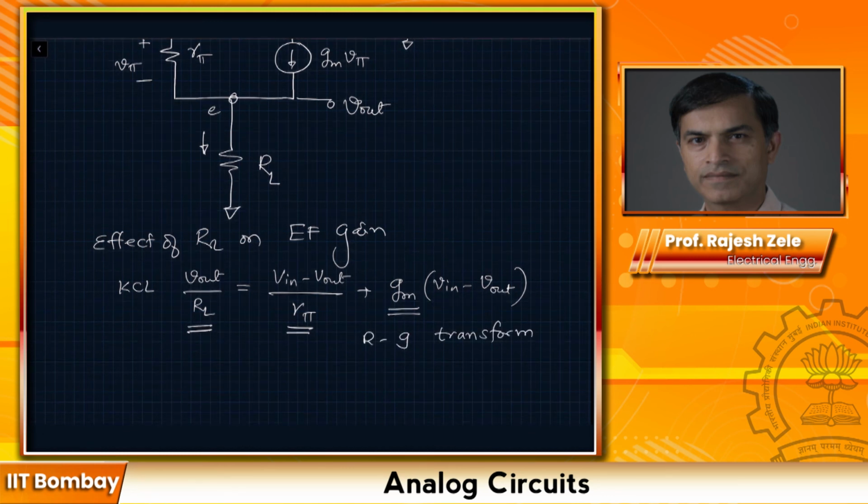So I like to use this trick to get a quick answer, and at the end I would substitute things back. So the transformation is GL is equal to reciprocal of RL and G pi is equal to reciprocal of R pi. If you practice it a couple of times, then you can solve complex equations very quickly.